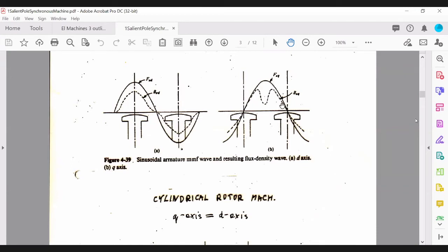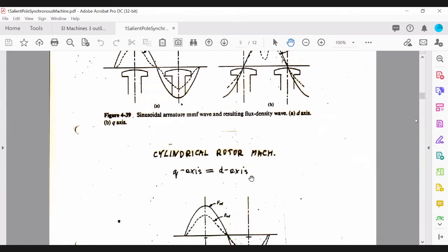So the frequency is twice that of the q-axis MMF. When we model the equation and add the component due to the q-axis, you will find that there is a difference in the frequency. That will reflect onto the reactance of the machine.